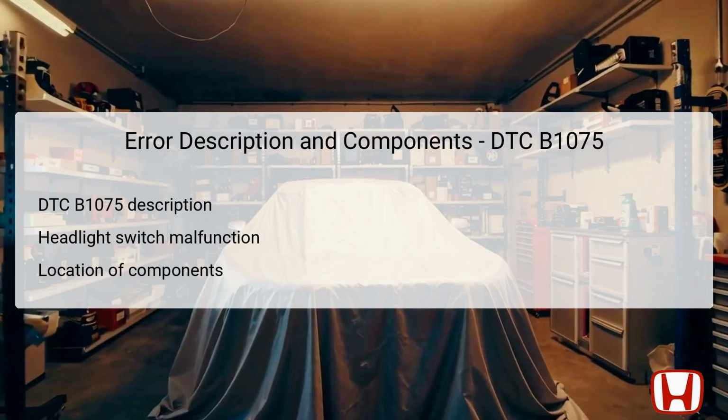DTC B1075 reflects a malfunction in the headlight switch backup circuit, meaning there could be issues with how the headlight systems engage. The headlight switch is critical as it controls when the headlights are turned on or off, thereby ensuring visibility during driving. This switch is usually located on the steering column or dashboard area and is easily accessible for usage.